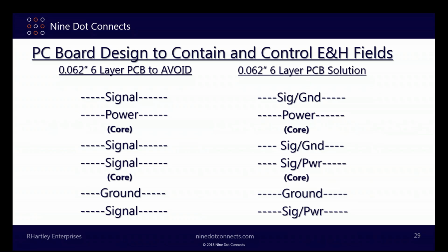What's the solution? The solution is to keep the same board stackup, except put copper pours on all 4 signal layers, and attach the copper pour on layers 1 and 3 to the ground plane with lots of vias. How many vias? A via every 20th wavelength of the maximum rise time frequency. Ooh, what does that mean? If rise time is 500 picoseconds, what's its frequency? It's roughly a gigahertz. Come to a class at PCB West, you'll learn why.